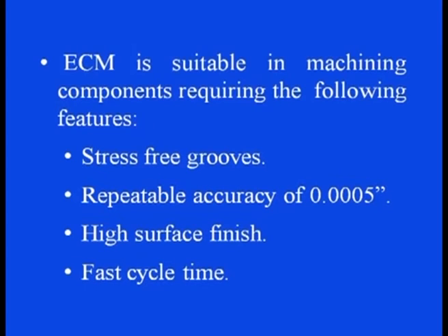ECM is suitable in machining components requiring the following features, like stress free grooves, as there is no mechanical machining phenomena involved in this process. Therefore, mechanical stresses are not developed. Then repeatable accuracy, something to the tune of 0.005 inches. Then the parts where a very high surface finish is required, at the submicron level, and where a fast cycle time is a requirement.